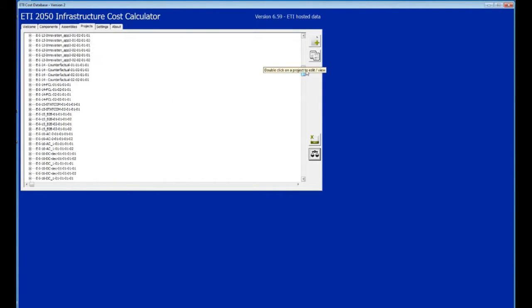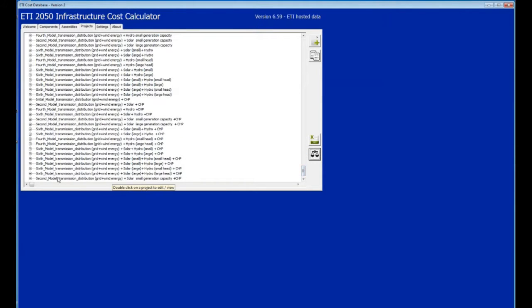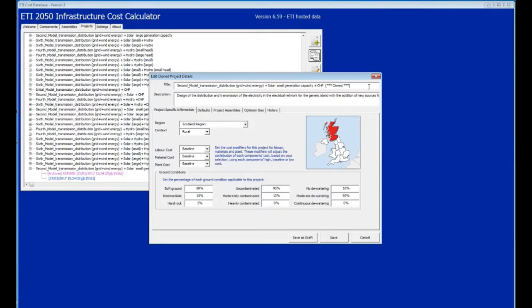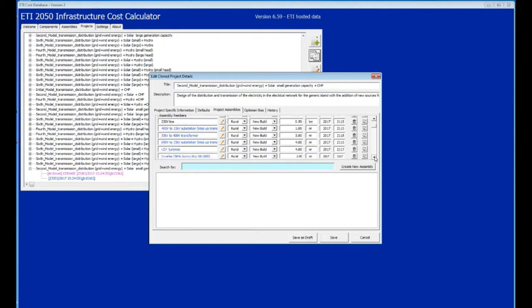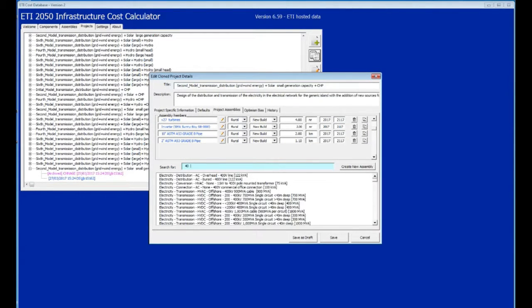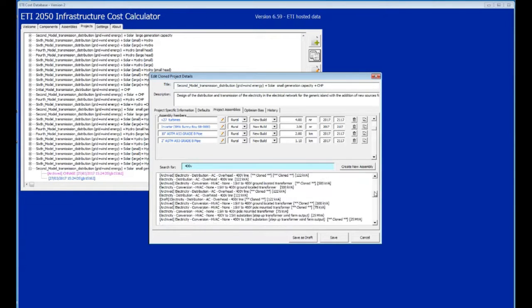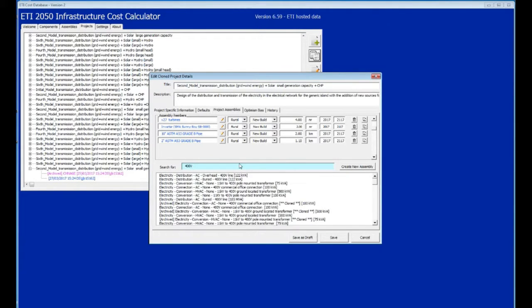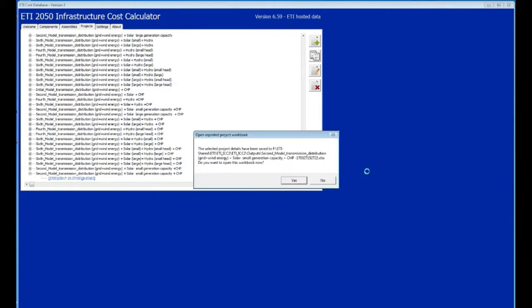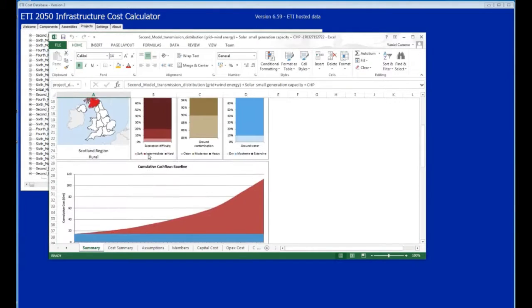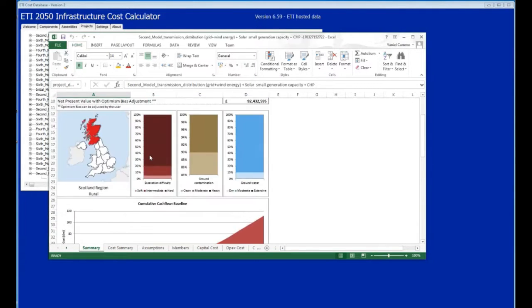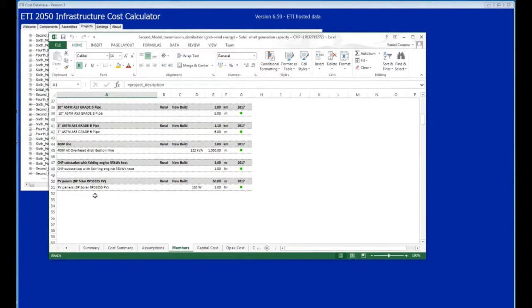Using the Energy Technologies Institute Infrastructure Cost Calculator tool, the capital costs and operation and maintenance costs for all projects were analysed. Figures were calculated through the development of a component list, which was then grouped into assemblies from which to build each project's financial study from. Projecting the net present value of each project over 50 years and stating CapEx, the payback period was determined. Using project costs alongside government incentives outlined by Ofgem, the cost of electricity per kilowatt hour over the project life was calculated.